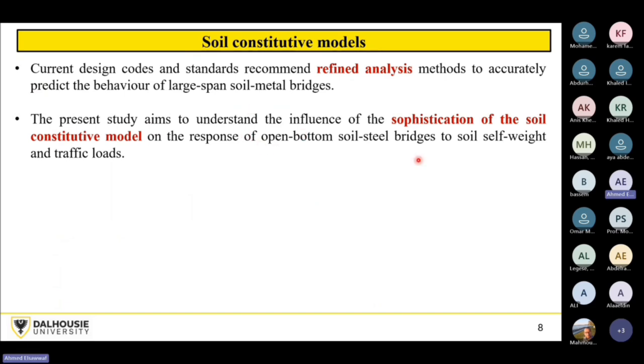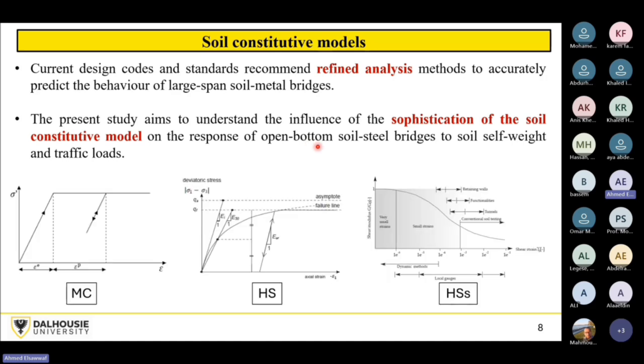So before going deep into my presentation, the last piece of cake in my introduction is the soil models that we can use in Plaxis. Here you can see that we have 3 popular material models: the Mohr-Coulomb model, the hardening soil model, and the hardening soil with small strain stiffness model. I just want to give, in 1 or 2 minutes, a quick introduction to the main basics that may affect our model. The Mohr-Coulomb model is very well known, and it features a bilinear stress-strain curve.